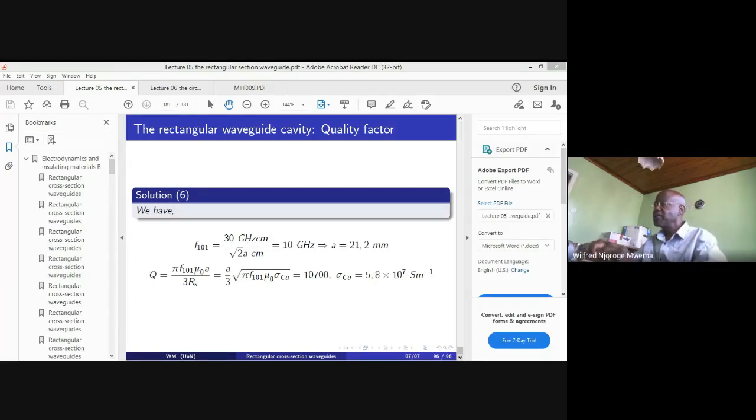Okay. There's a guy who says, of course, they are radio signals, but the question was what kind of waves. So mainly we can say that when they leave the antenna, they will be in the form of TEM waves that are spherical, that is, they are radiating in all directions, especially if we don't have a reflector. And then as they get near to your phone, we are very far away from the source, and therefore the wave will be almost like a plane wave, because in any case, the antenna in your phone is so small that it can only pick a very short section of that wave front. So it will appear to it for all practical purposes as a plane wave. But they are all TEM waves.